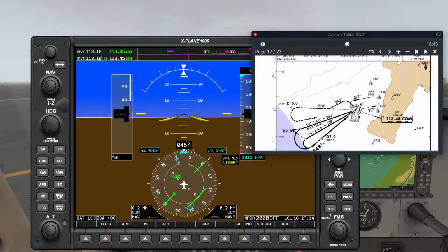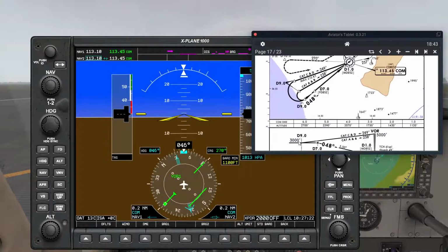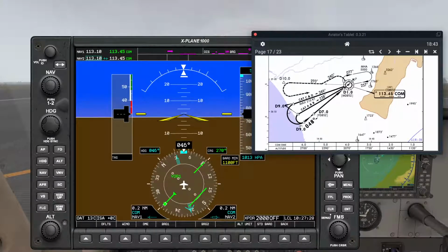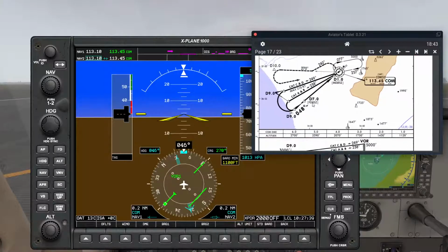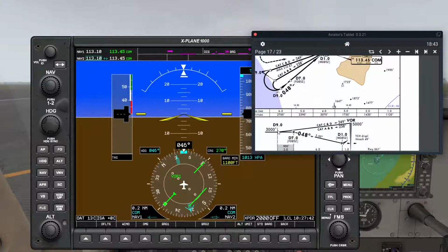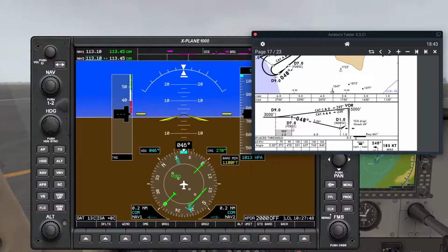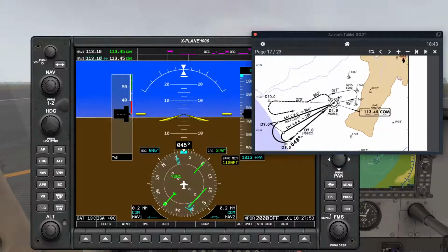Enter the holding, and after that for Cat Alpha and Bravo aircraft, follow the radial 238 descending 3,000 feet, leaving 5,000 feet, descending to 3,000 feet at 9 nautical mile out of VOR on radial 238, then via left turn proceeding on course 048 to join the final. After 9 mile inbound maintaining 3,000, after 7 mile inbound on final course descending to minimum, which is 1,100.